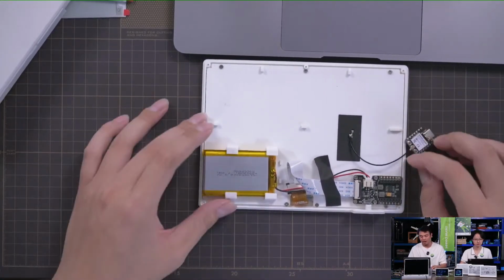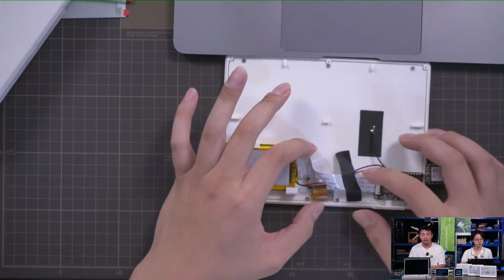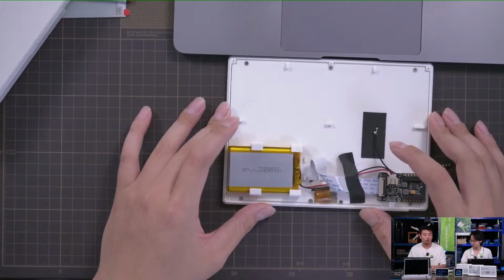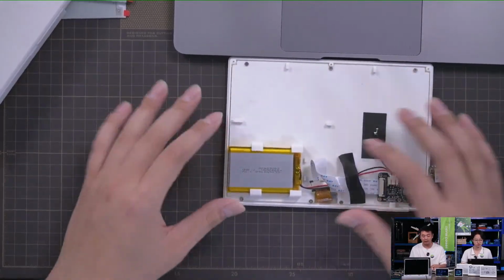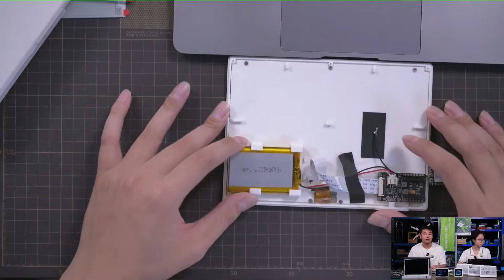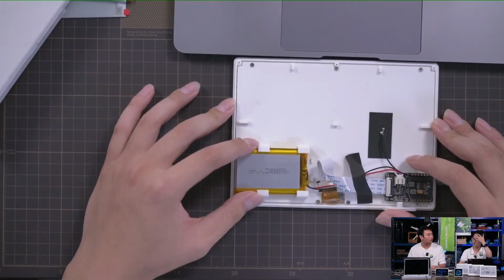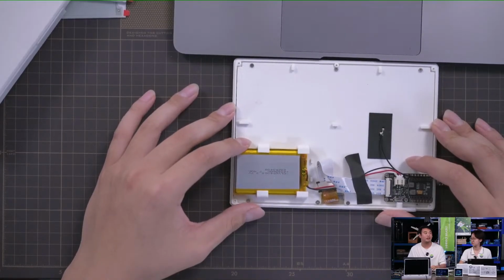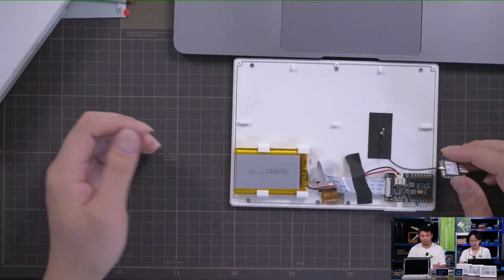Here is the driver board for the ePaper, and we connect a 10 cm FPC cable, which is very flexible when you want to redesign the case or the components. The battery is 2000 milliamp hours, and it can run almost 3 months if you refresh your data every 6 hours and stay in deep sleep mode the rest of the time. Okay, so long.